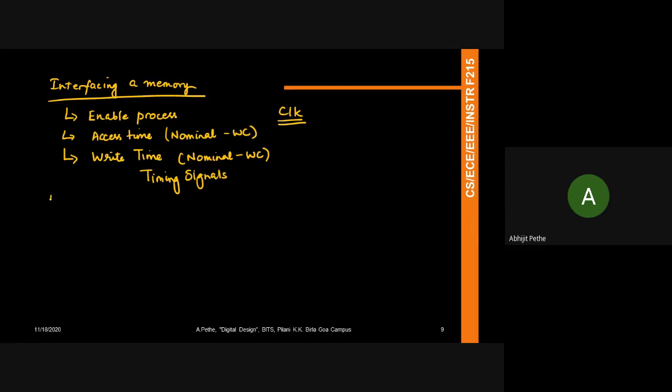Now let's think of a block diagram of a simple memory cell or a bit cell. Let's recall what we said about the bit cell in the last class. We said that the bit cell can store a 1 or a 0, so it is a 1-bit storage. Now I'm going to discuss how we connect these bit cells together to form a particular memory. Some of you alluded to it last class, saying that we need to use a decoder, and you're right. So we'll complete this by figuring out how to connect these various bit cells to create a memory which takes in a word or gives out a word.